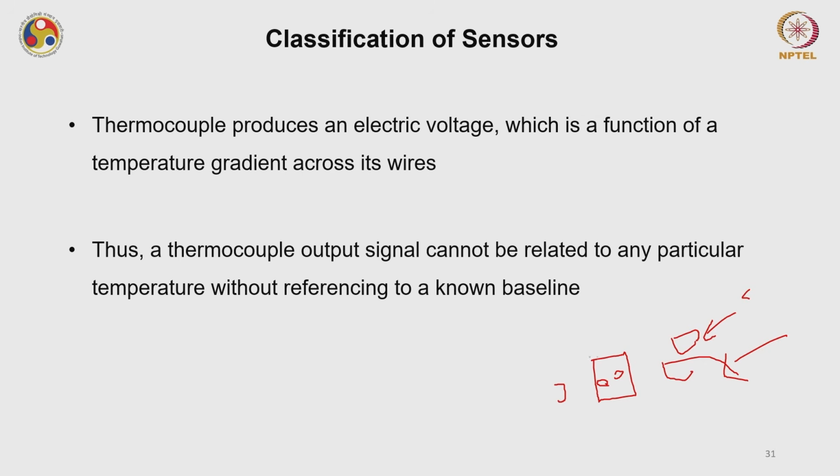Now say a signal S1 is detected at the reference infrared detector, and a signal S2 is generated at the second infrared detector. I can compare this S2 with S1. If I compare them, I may know whether there has been some absorption by the gas molecules.